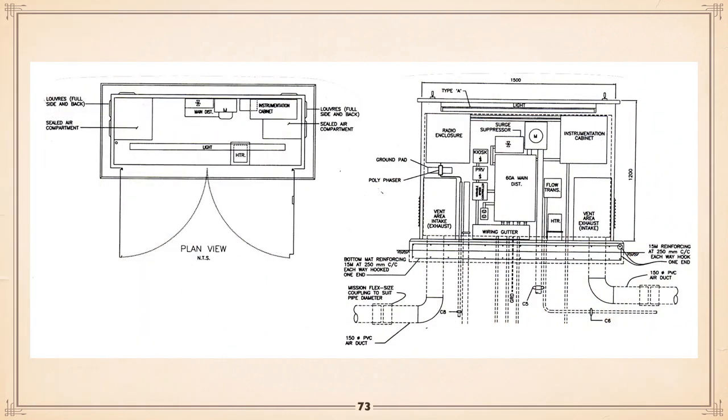Let me show you. There is a single kiosk. As you can see from the left drawing, all the electrical metering, the incoming service and everything is there. But on the right drawing, you notice about halfway down on the left bottom and right bottom, you can see where we've got ducts coming into a chamber which has louvers on the outside. That way, the air for that underground chamber is coming from there, and away you go. And you can see the type of equipment that would be involved. Typical servicing. In this case, you're servicing nothing but instrumentation. But pump stations, submersible sewage pumps, you get into them.